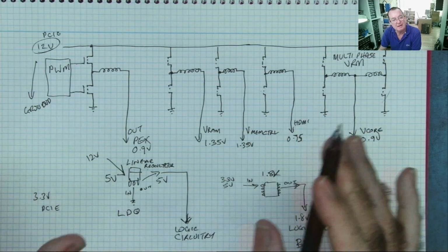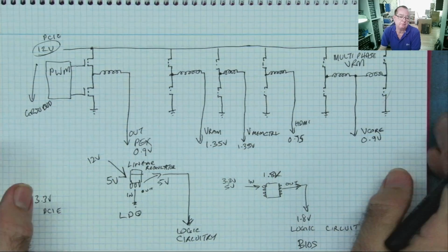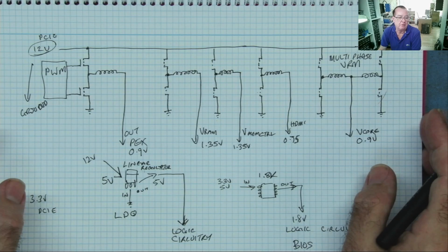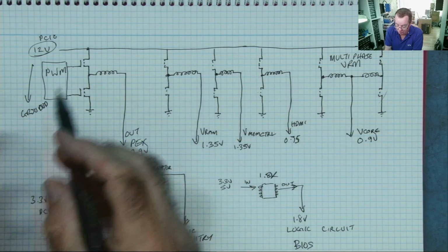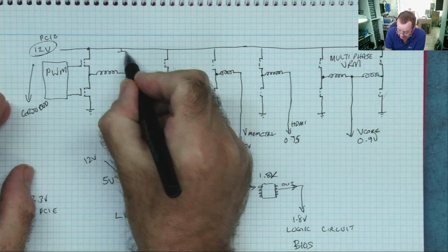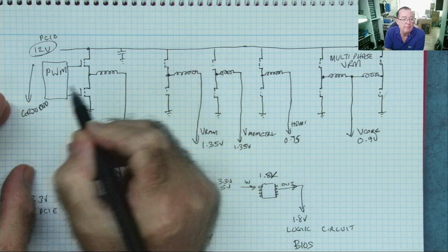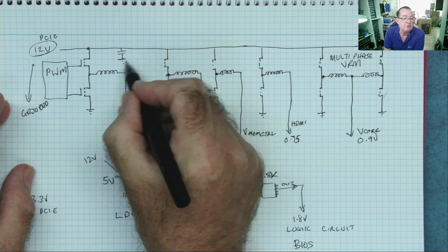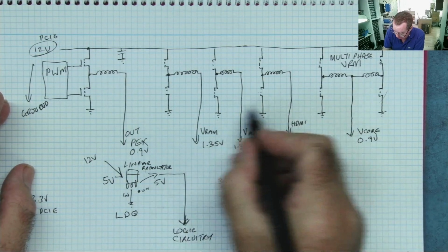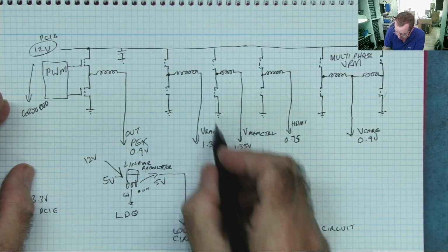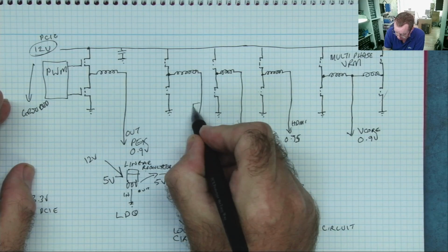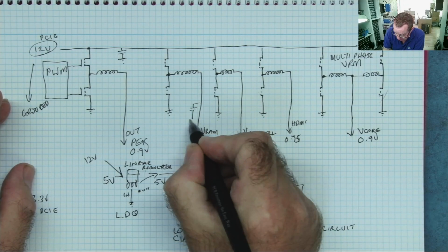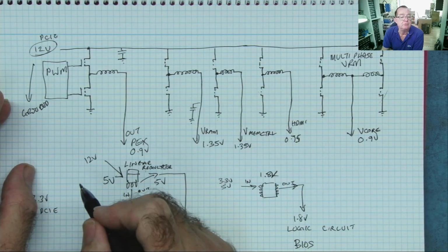If you find that, there are two likely causes of it. Okay, one, on here there are capacitors. We'll look at some of them when we look at the graphics card. Again, this is the ground symbol. These could be short circuit. There's also, from all of these voltage rails, there's capacitors on all of them and lots of them to ground, and one of those could be short circuit.